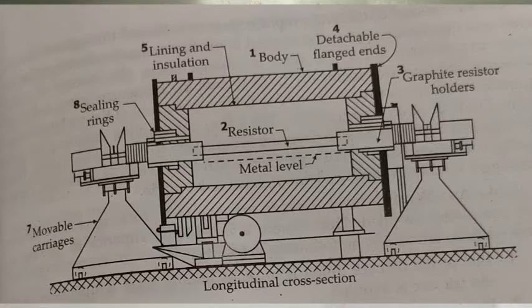Provision is usually made for automatic control of the rocking motion, the amplitude of which is adjustable. The white hot graphite resistor gives good reducing conditions, and no slag covering is necessary to prevent oxidation. These reducing conditions permit very high yield when alloys such as cadmium copper, containing a readily oxidizable element, have to be made.